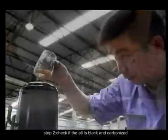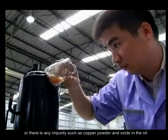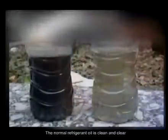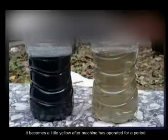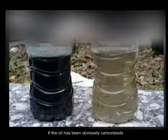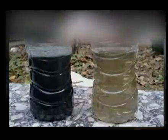Step 2. Check if the oil is black and carbonized, or if there is any impurity such as copper powder and oxide in the oil. The normal refrigerant oil is clear and clean. It becomes a little yellow after the machine has run for a period, but it should remain clear. If the oil has been obviously carbonized, it is forbidden to change only the compressor.